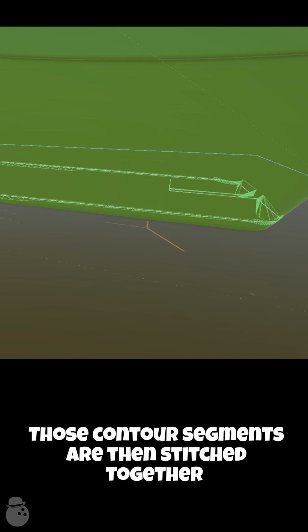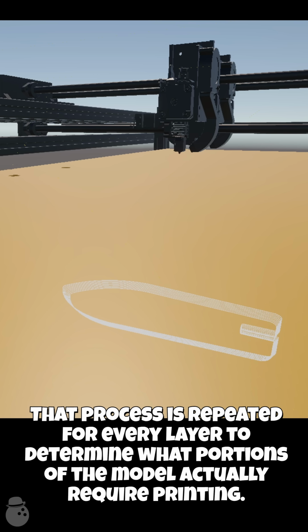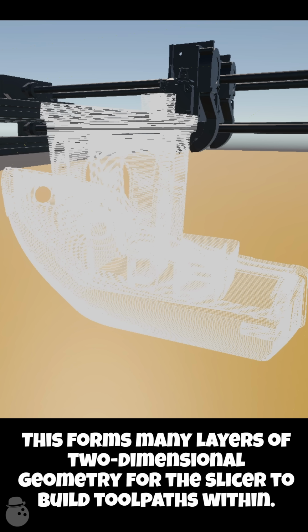Those contour segments are then stitched together where their endpoints overlap to form closed loops. That process is repeated for every layer to determine what portions of the model actually require printing. This forms many layers of two-dimensional geometry for the slicer to build toolpaths within.